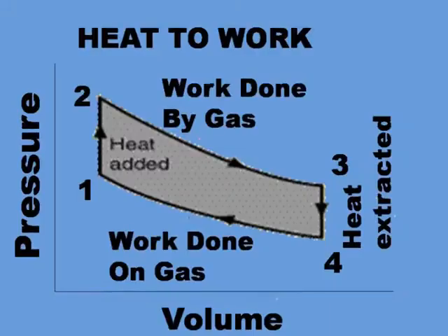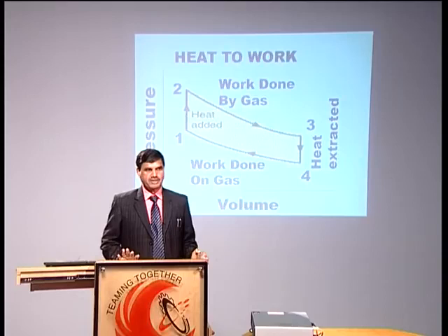So, this type of cycle is also not 100% efficient, but at the same starting pressure values, this cycle is better than the diesel cycle which we are referring to. It means constant volume heat addition is much more advantageous as compared to constant pressure heat addition as far as efficiency is concerned. Other effects on the engine which come due to this type of heat addition we will discuss later, but to conclude the heat addition processes, we have discussed three types: one at constant temperature, another at constant pressure, and the third at constant volume.